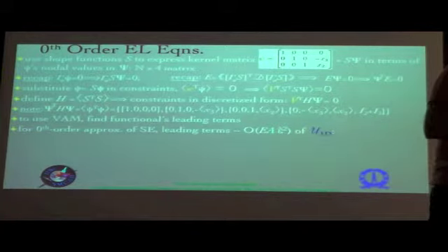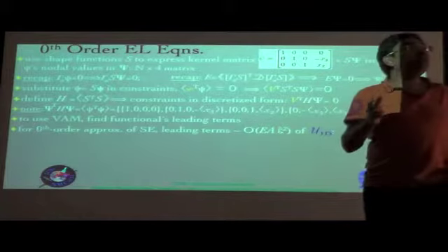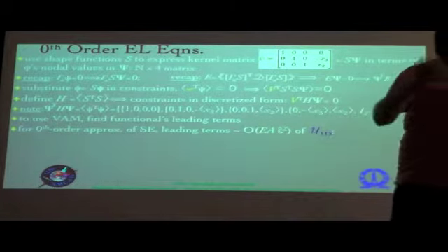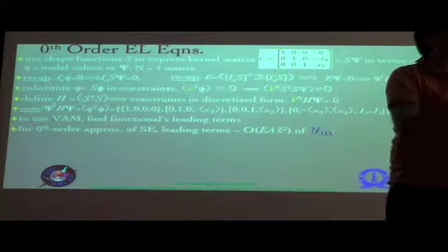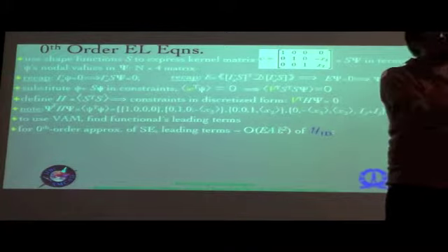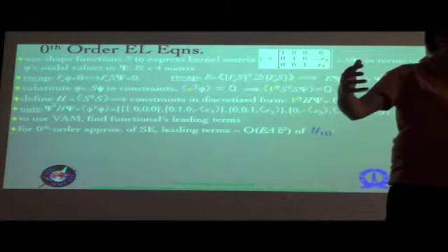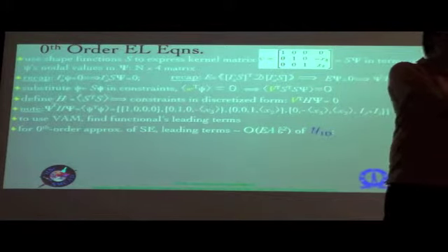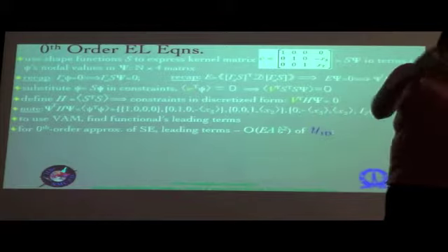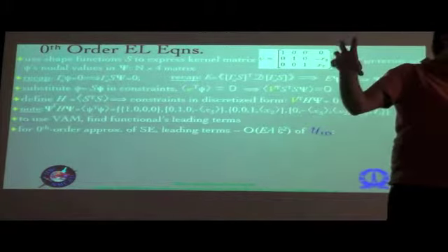See, the root G comes into picture only if an area integral is inbuilt into a volume integral. So for example, your total energy of the beam is equal to the volume integral of the 3D strain energy density, right? That volume integral can be broken up into two parts, the integral over the cross section and the integral over the length, right?